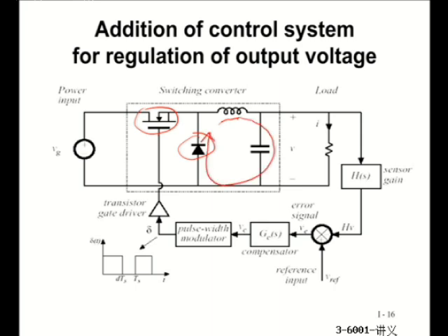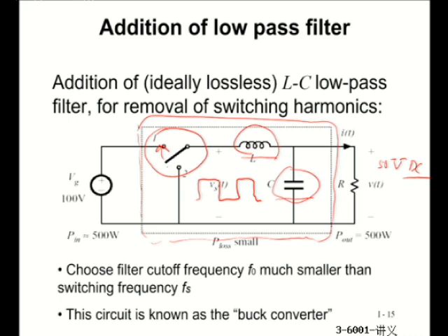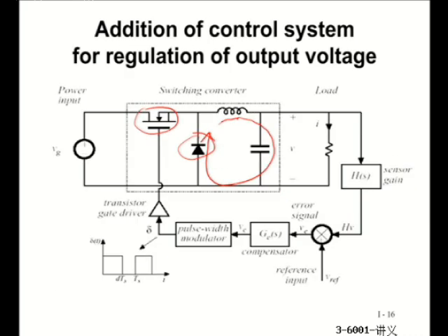It will be exactly like this switch connected to position 2. So a pair of semiconductor devices, such as a power MOSFET or IGBT, together with the power diode, will make this SPDT switch.